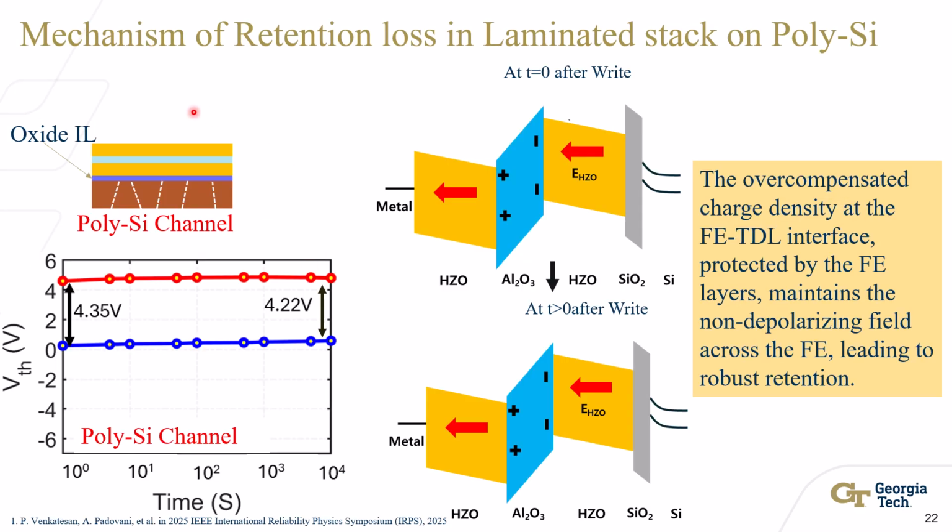So let us try to understand the mechanism of retention loss in laminated stack on polysilicon channel. In case of a polysilicon channel, we see that the device's threshold voltage does not change over time, and the memory window is stable, thereby leading to robust retention even at 10,000 seconds.